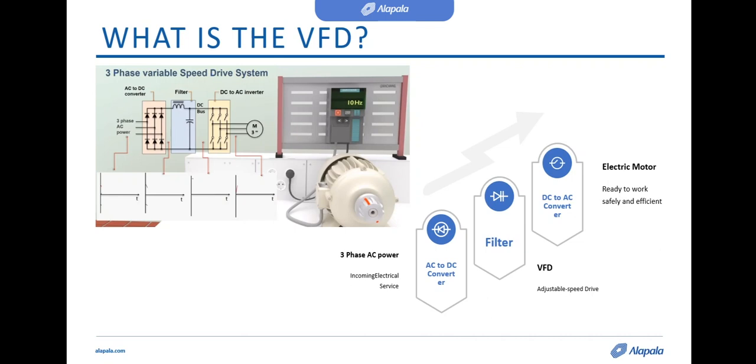This block diagram illustrates a typical three-phase AC variable speed drive system with its main components. First, incoming AC voltage enters a bridge rectifier, which consists here of 6 diodes. In the middle stage, the DC voltage has ripples. Therefore, a capacitor and filters have to smooth out the ripple. Now, the DC bus system can take its place.